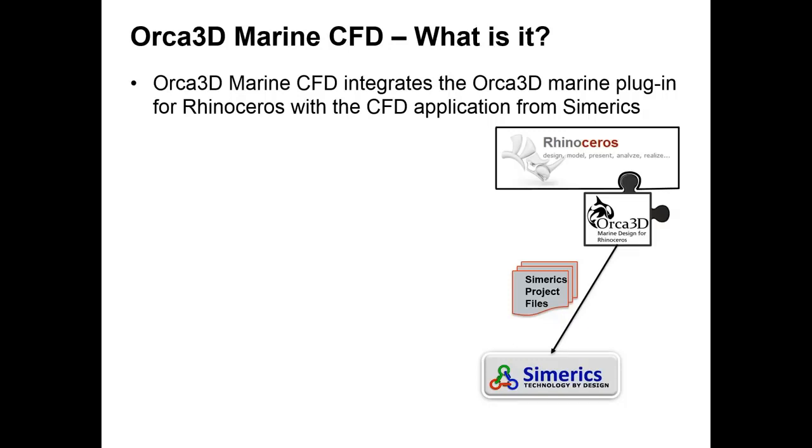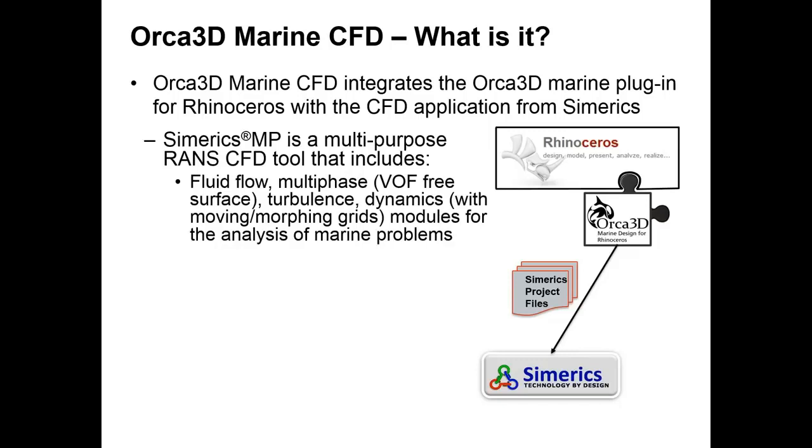One of the primary objectives in implementing this CFD integration was to follow the same philosophy as the rest of Orca3D by making it easy to use. For those of you who may not be familiar with Simerics, Simerics MP is a full-featured, multi-purpose CFD tool. As integrated with Orca3D, it includes those modules which are commonly needed for the analysis of marine problems, including a general fluid flow module, a multi-phase flow module using the volume of fluid free surface, a turbulence module, and dynamics.